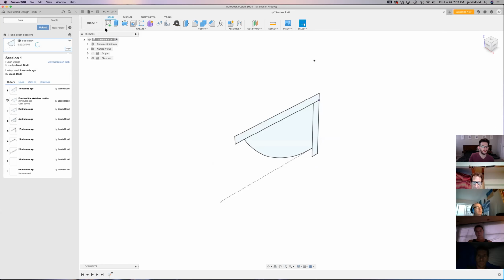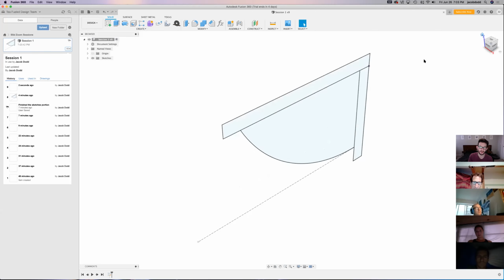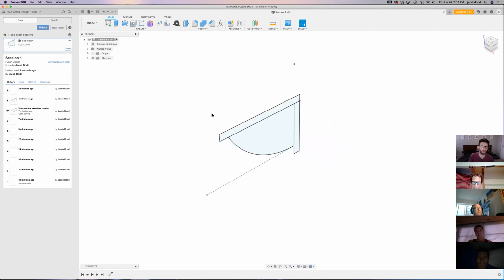Cool. So yeah, we're in our 3D view here. We can use the cube to rotate around the home view to get it into a nice 3/4 angle. And what we're going to do from this is, because we're just doing a flat profile, we can use the extrude. So E for extrude, or as per usual, S, and then search for extrude. And you're going to want the blue version because we're working with solid models.